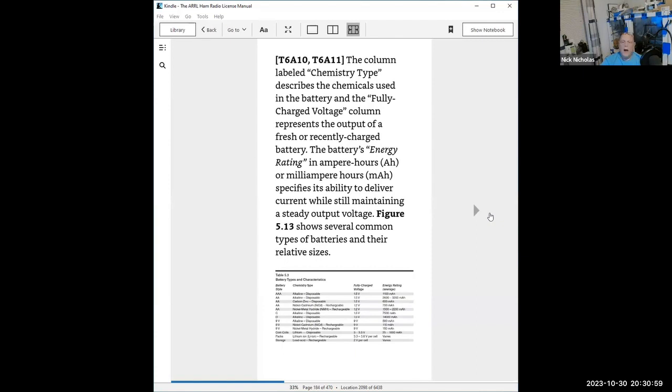No, it will not, because not all battery chemistries allow you to draw 100% of the amp hour rating out of them. Some batteries, like primary batteries, which are not rechargeable, are designed to run till they go dead. Some rechargeable batteries, like lead acid batteries, are only designed to go down about 30% before you do them damage. Lithium batteries can go down to about 90%. But a lithium battery that goes to 91% becomes what they call a violent exothermic anomaly, meaning it bursts into flames and you can't put that fire out.